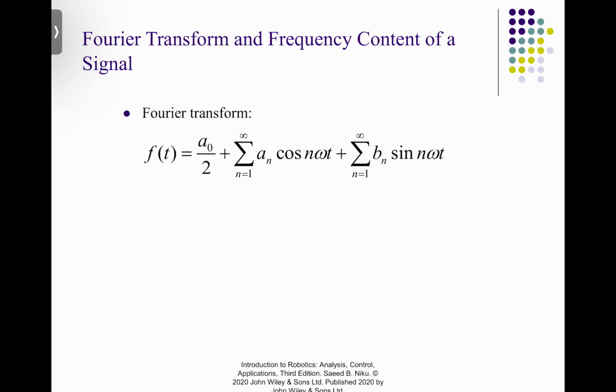But please understand, to apply Fourier series, this signal needs to be continuous. It should go from minus infinity to plus infinity. So that periodic signal should be repeating. It should be periodic and it should be repeating. Only then you can find out the Fourier series.